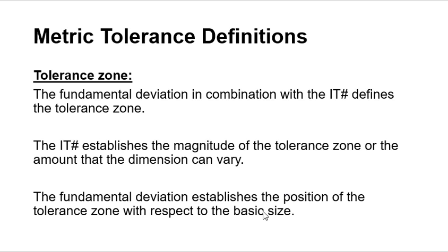So you can understand that the basic size and your limits, the tolerance zone range, they're all connected. It's just the way that they're writing in English, they confuse you. If you see the upper limit and the lower limit, your max and min, and then your basic size is somewhere in between or on it, you kind of get it. It's just telling you the same thing here by using the symbols, and a different name for these definitions. Don't worry about it, just read it. You will get it.